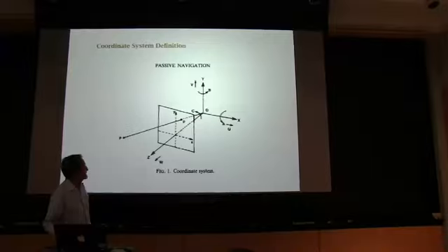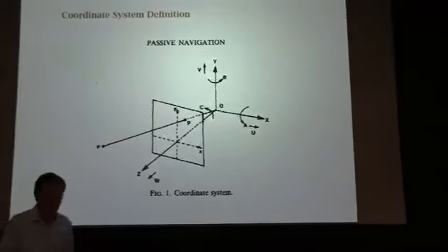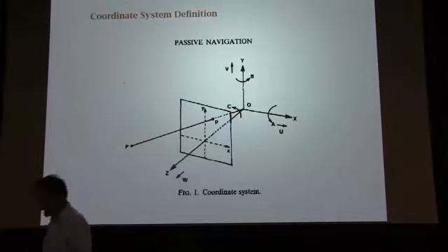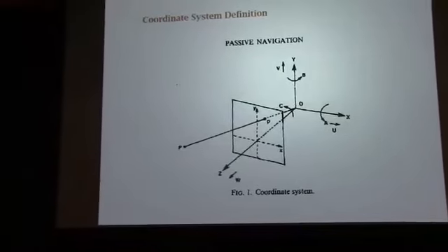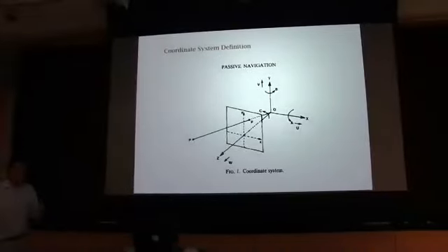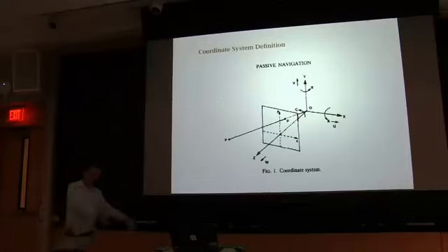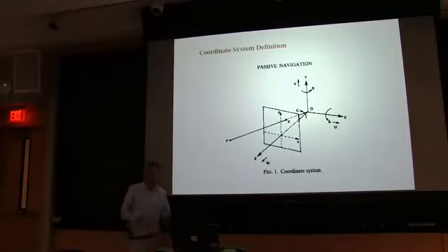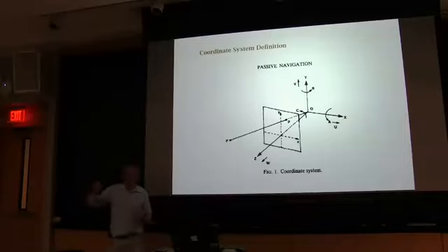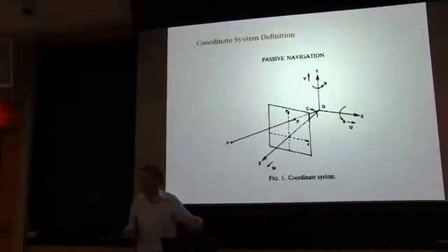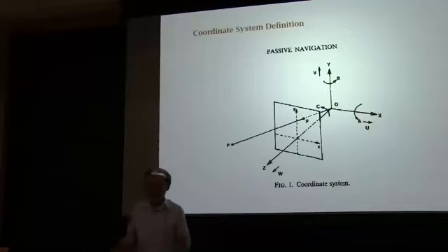So we'll be talking a little bit about coordinate systems and transformations between coordinate systems. For example, in the case of robot applications, we'll want a transformation between a coordinate system that's native to the camera and a coordinate system for the robot, which has kinematics programmed into it so that you can tell it in X, Y, Z where to go and in angle how to orient the gripper. But that's in terms of its defined coordinate system, which is probably, the origin is in the base where it's bolted to the ground.